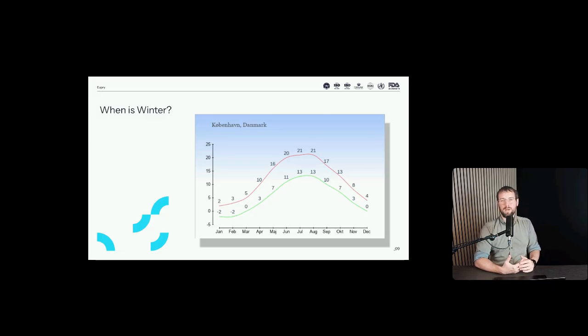Well, it might not matter that much, because when we define a cold spot, we'll place a constant temperature monitoring sensor there. Subsequently, during our constant monitoring, we can see whether we go outside those limits. The cold and the hot spots basically tell us where it is coldest and where it is hottest, and all other temperatures should, to a high degree of certainty, be within those two. So as long as we follow it up with constant monitoring in the coldest spot, it should not matter that much if your outside temperatures drop below those limits.